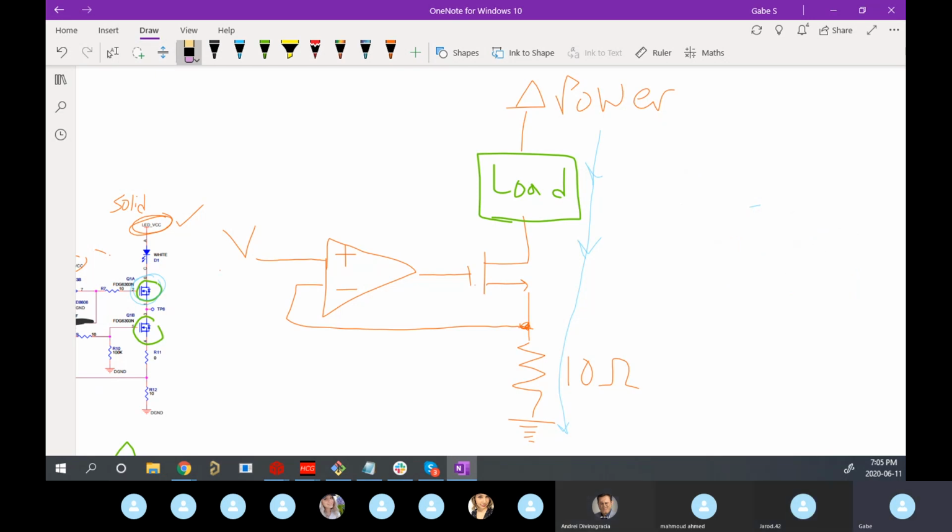So essentially, what you're doing here is maintaining the current in this path no matter what's happening with your load. And it's super cool because if you were to try and control the current in a path, you'd need to switch between different resistors, and maybe use something like V equals IR, so if you change the R, the I will change. And usually we have control over voltage. Remember Jared has talked about linear regulators and buck converters, so we know how to regulate and change voltages at will. But changing current isn't as fundamentally easy or as intuitive.